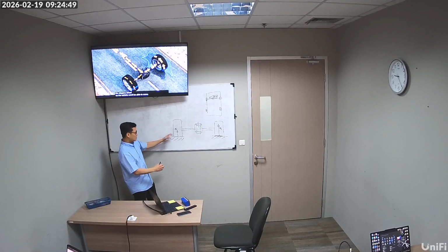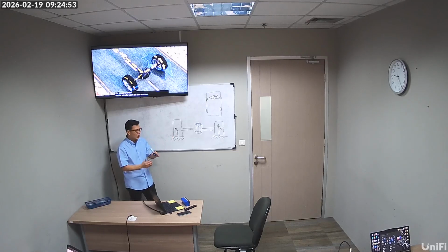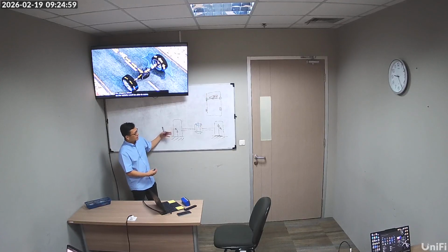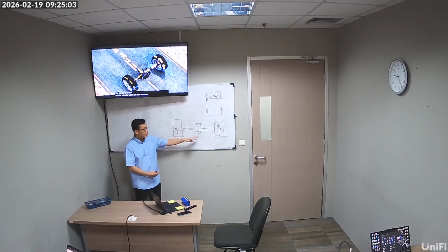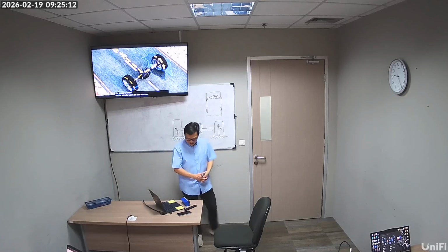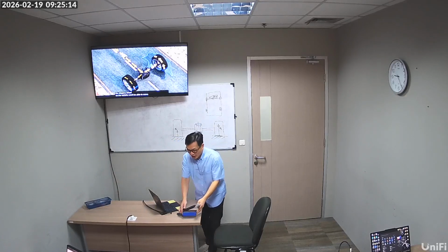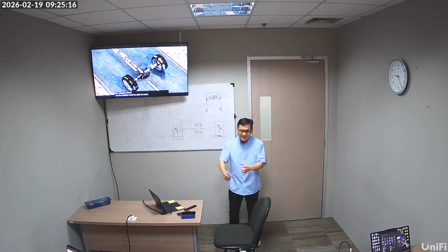But this one will slip first. Maybe some micro slipping, not a full slip, but some tire slip. And if they have just a little bit of a slip, the torque will be bigger here, which is the opposite of what we want, right? So this becomes a real problem, even not in the accident situation, but even in racing situation.